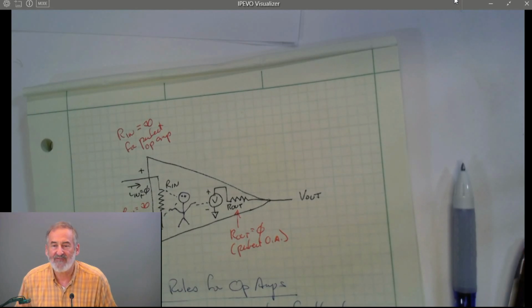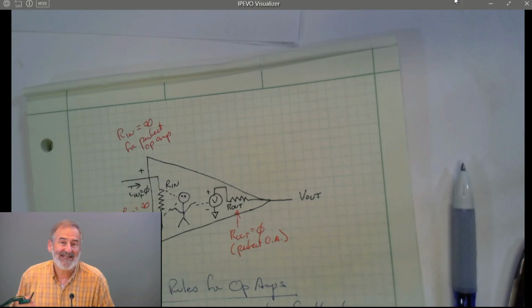We saw that in the emitter follower where VBE had a very strong temperature dependence, and of course as VBE changed, the collector currents changed, which caused our operating point to change. But when we put a resistor RE between the emitter and ground, as the transistor got hotter and VBE decreased, the collector current increased. That causes more current through the emitter resistor. That causes the emitter voltage to go up, which decreased the collector current. And it kept the collector current relatively constant. That was an example of negative feedback.